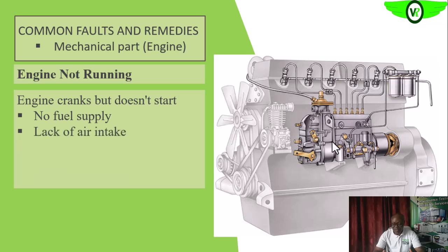So remember, for combustion to take place, we need air. If the air filter is plugged, of course, or even if it is taking air, the volume of air that is administered into the combustion chamber may not be enough, which could be affected by temperature or heat, because the hotter the air is, the less concentrated it will be.